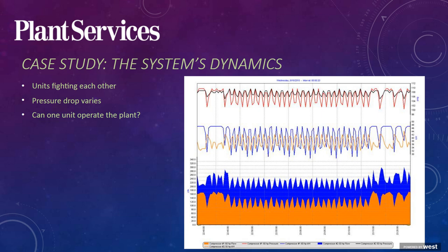Getting back to our case study, average compressed air supply was about 240 CFM, so you kind of slice the middle there with the flow on the bottom of the graphic at right. And the required plant pressure was only 95 psi, so we're amply meeting that with the system we have. The supply range of compressed air was about 200 to 300.